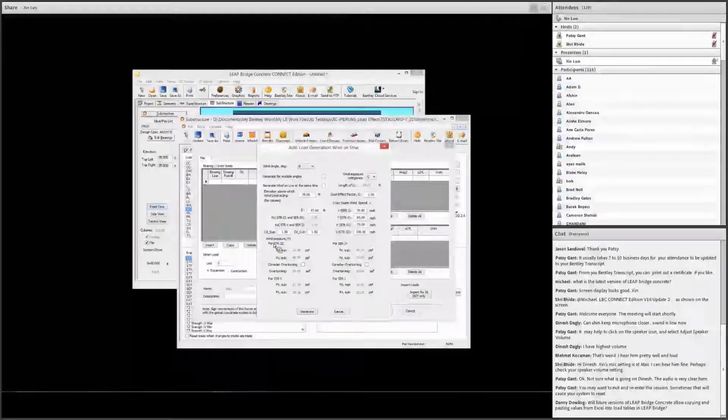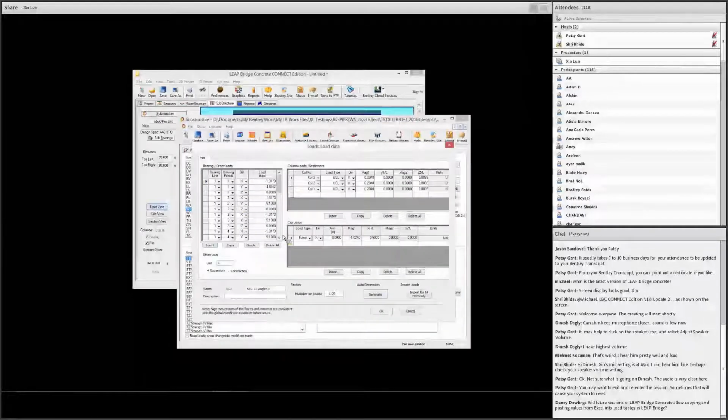So we can see the auto-generated wind pressures. Strength 3 shows the wind pressure here. Service 4 shows the generated pressure here, and so on for strength 5, service 1. This is for the horizontal. If we want to consider the overturning, consider the vertical wind pressure, we check this box, and we can use the default. If this is unchecked, the default value is calculated here. But if we want to override the program calculated value there, we can check this box and override it. So let's just use the default values there and click generation. Then it will generate the wind load.